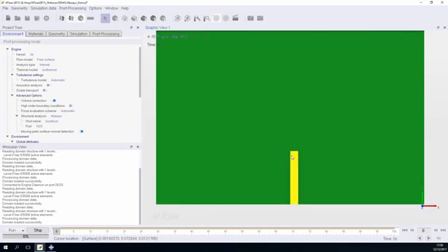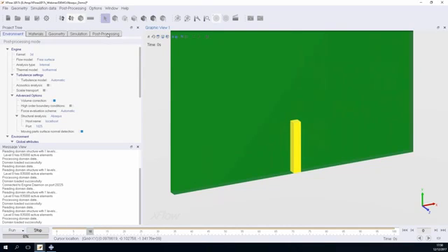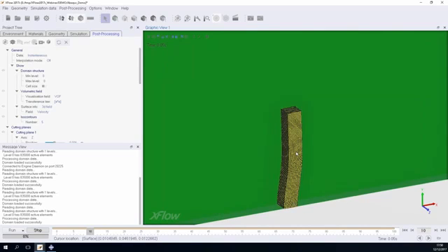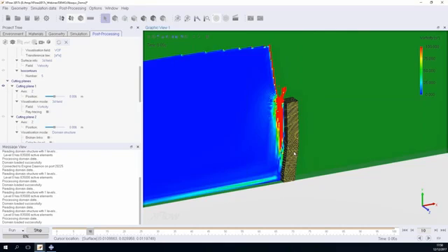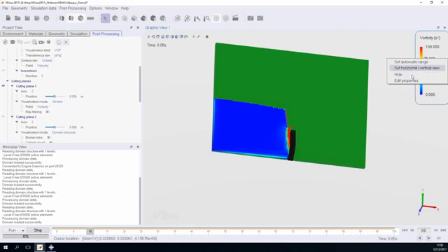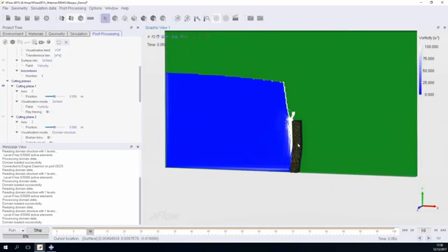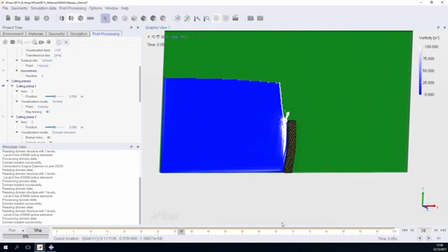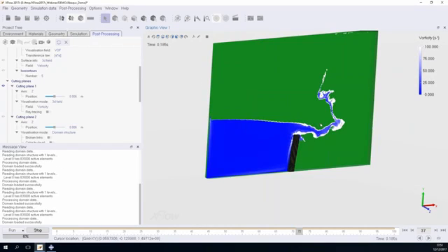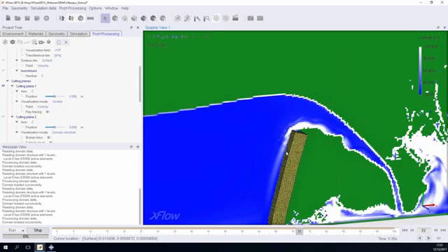So that's the exact same setup, but as you can see now we have a complete simulation. So if I move in time and show some of the steps, you can see that the geometry starts to deform, of course, and if I set a few cutting planes here and there, you can see how the fluid interacts with the geometry. Okay, let me set that exactly as the video so you can see where the video comes from. And if I select a different time step where I saved my data, you're going to see that our geometry is actually being deformed by the forces acting from the fluid side.